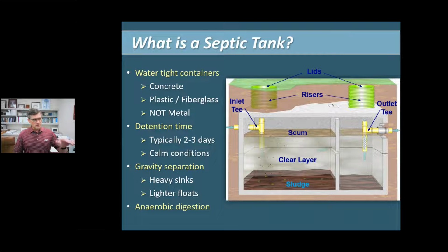So detention times, talk about that. Then we think about the gravity, we think about the separation. So the inlet coming in, your solids settling out. If there are any lighter pieces, they may flow over through the baffle into that secondary chamber, and you'll start to get a little bit of sludge there. So if you see it there, don't be alarmed. It's fairly common. All right, and when we think about aerobic, anaerobic: aerobic, we think about air; anaerobic, the lack thereof.